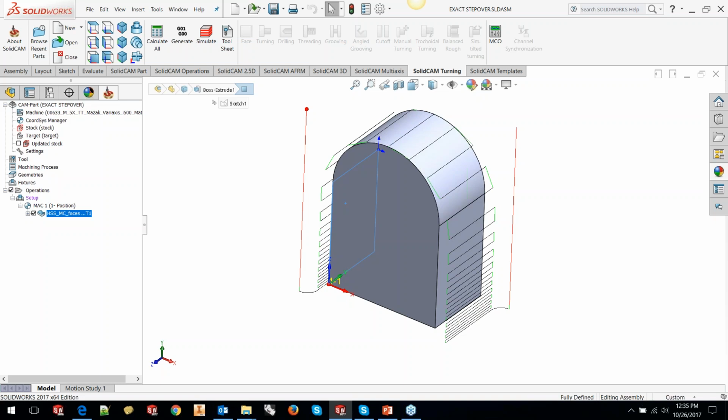The end result is that you get non-uniform step over. Sometimes it's really very large. If you're given a depth of cut of 1 millimeter, it can sometimes end up to 5-6 millimeters in some areas, depending on the steepness of the area and also the width of the surface.